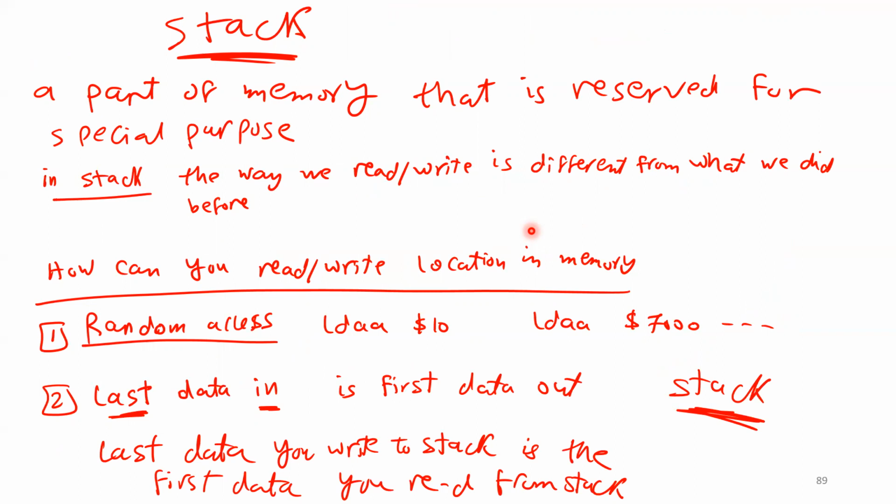The last thing I explained is, if you have a byte, how can you check some bits, how can you check if they are 1s or 0s? We're gonna do this all the time, because here in the board, as I'm gonna do in chapter 3, every switch is connected to 1 pin, and the pin is connected to a bit, right? So if I want to know if the switch is connected or not, I need to know if this bit is 1 or 0. I don't care about the other bits. This is one thing I explained.